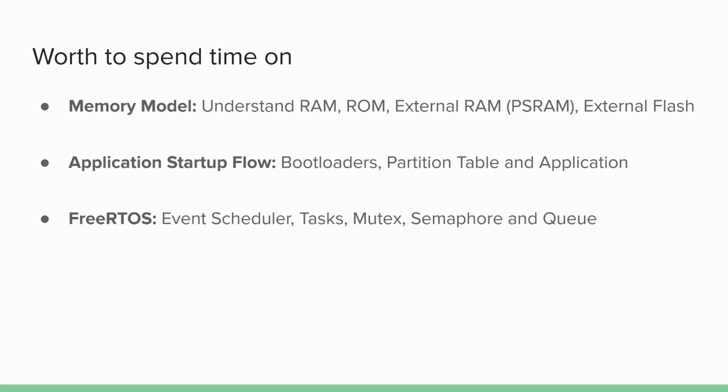So what you need to understand is the event scheduler, how FreeRTOS is scheduling our tasks, and then how you can create tasks, and how you can use mutex, semaphore and queues to build a complex application where you can manage the complexity and keep the inter-process synchronization aligned.